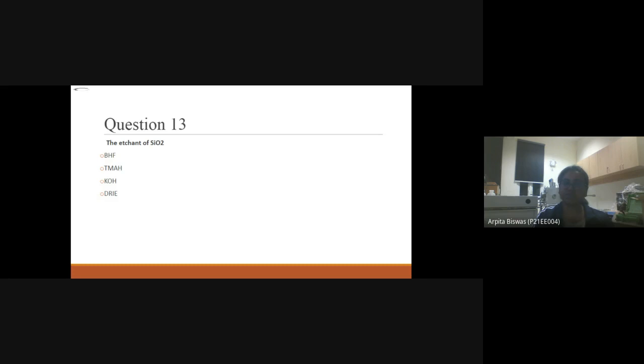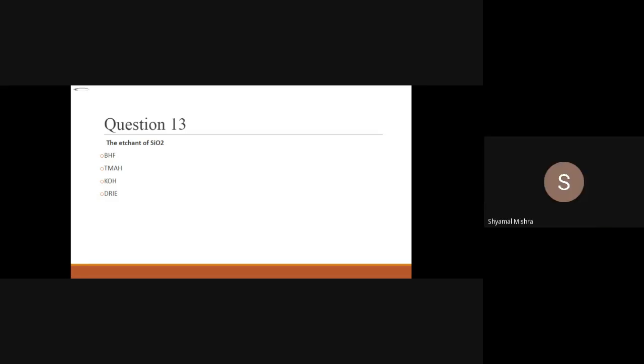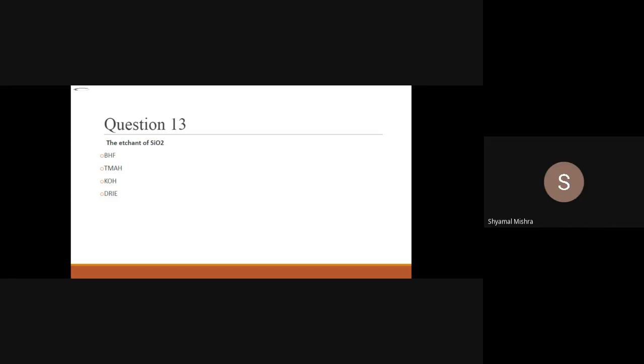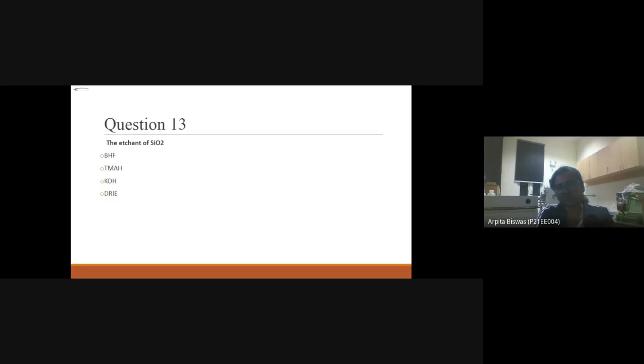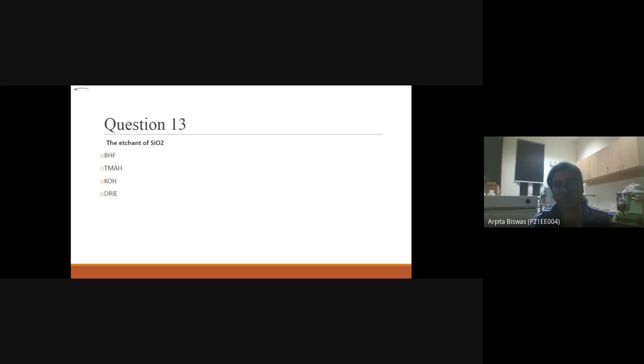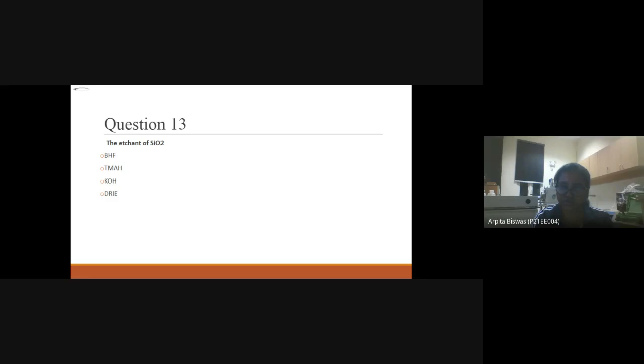So Shamal, what is the right answer here? The SiO2 etchant is BHF. Okay, and is it isotropic or anisotropic? Isotropic. Yes. And TMAH? TMAH is anisotropic. Yes, TMAH is anisotropic. Why is TMAH anisotropic? You are saying it's because it's etching from all sides. No, no. If it is etching from all sides, then it is called isotropic. If it is etching in a particular direction, then it is called anisotropic.